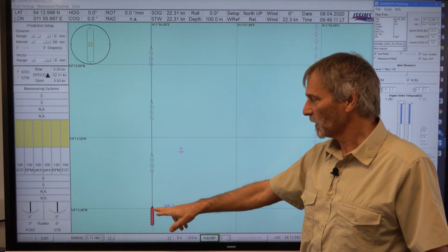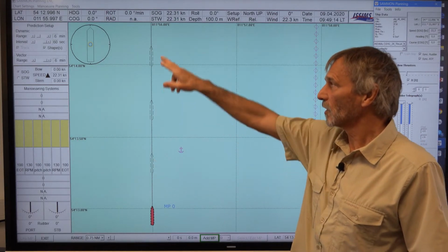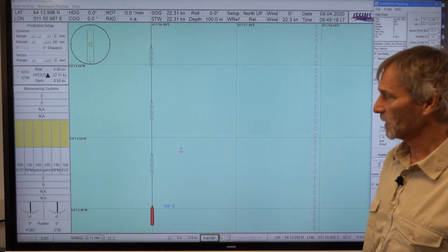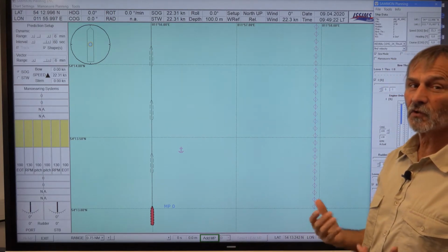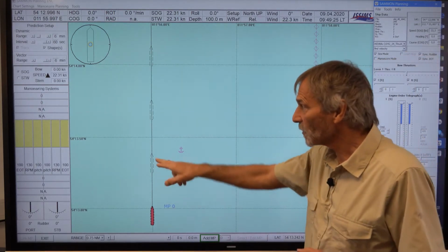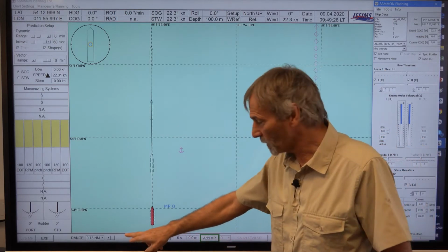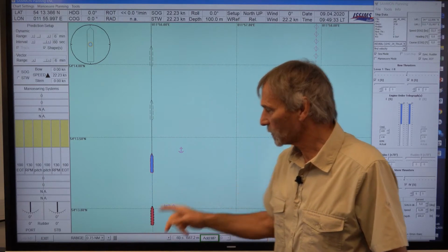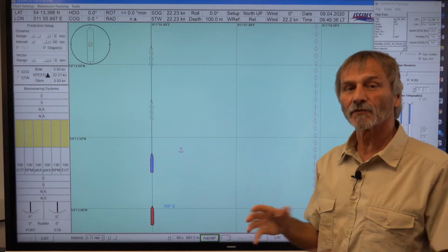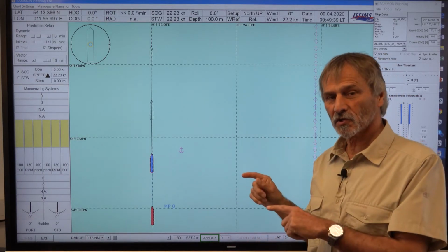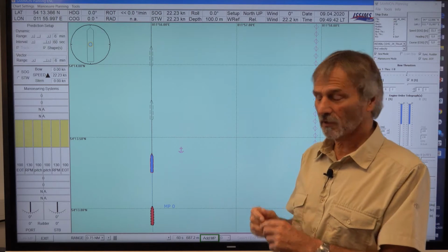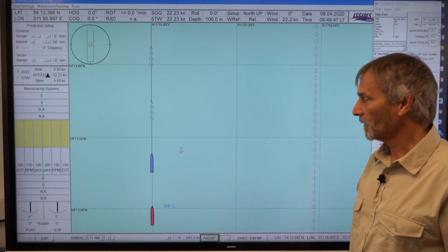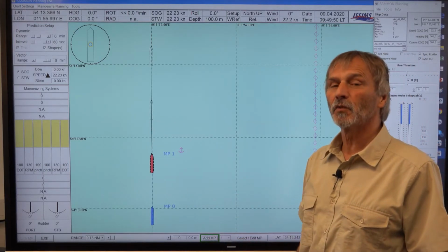And the fast time simulation provides the position of the ship every minute up to 24 minutes ahead. For the time being, it's 6 minutes. And the good thing is, if you want to see what happens on this track, then you move a reference position, like here, which you can click every 10 seconds, for instance. So now the ship is moved into second position after 1 minute, and this is the position where we will start our stopping maneuver. For this reason, we add a maneuvering point here, and then our focus is on that maneuvering point number 1.